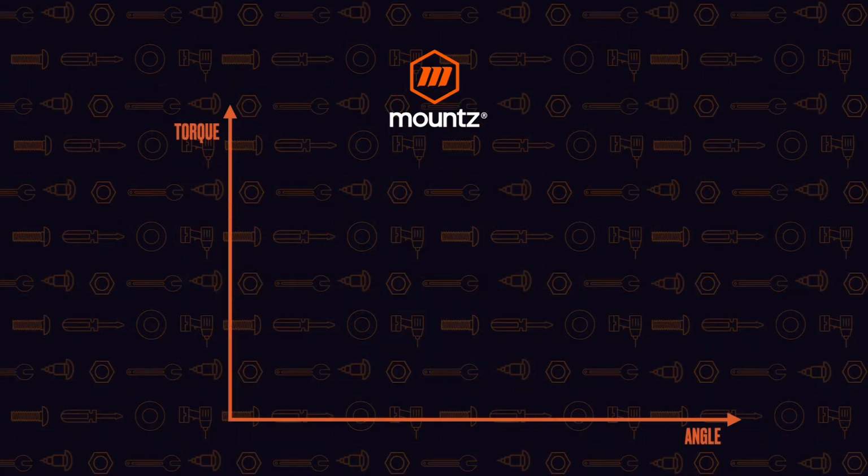And so if we look at that on a graph, when we apply load to a fastener and we've reached the torque value, then we remove the tool. There is the amount of torque that was used to fasten that bolt or screw. But there are some frictional forces that we need to overcome to be able to move it again to check it. And so this is kind of an example of just the coefficient of friction.